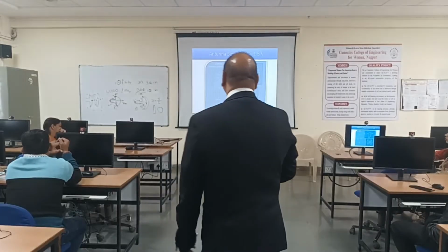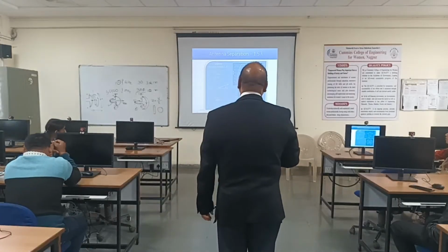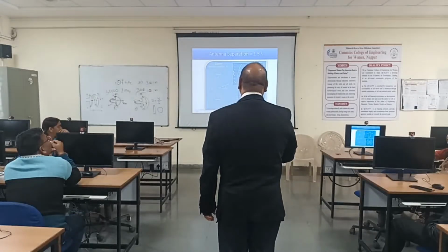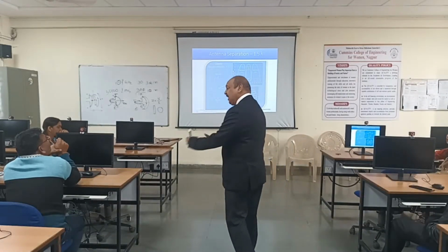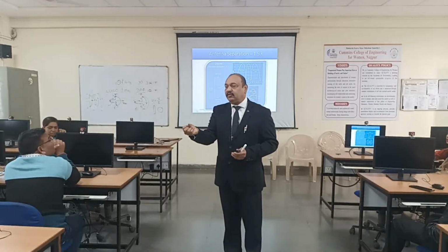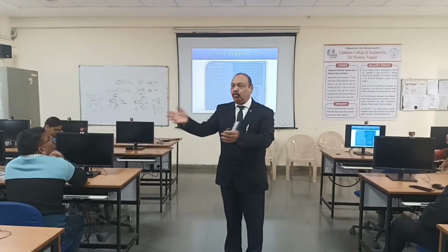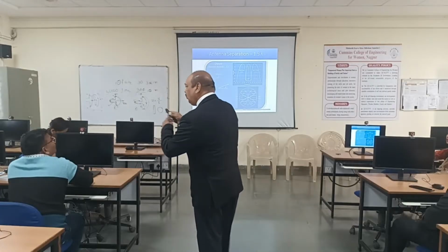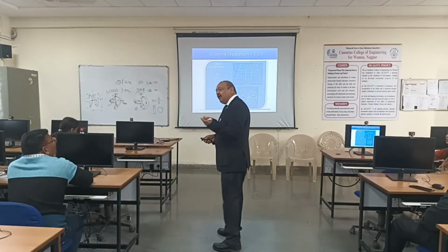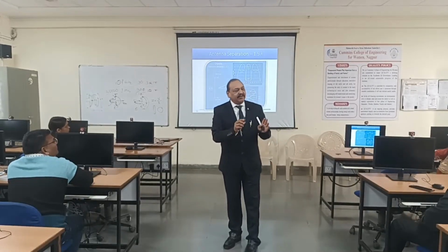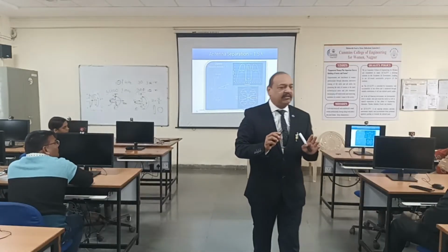Okay, next. Then if you go for 1.5 lambda, then this becomes further narrower. And you will get two sub beams, and accordingly this is the main lobe, these are the other lobes, side lobes. This is another side lobe you are getting. Means now your power is getting scattered, so gain should go on decreasing if there is a larger number of lobes. Means it's a wastage. Power goes into the lobes, so there should be a minimum of lobes, or there should be no side lobe and no back lobe. But such an ideal antenna we can never fabricate or design. There must be some, but from this we have to see that as little power as possible goes into the side lobes, that is the motive.